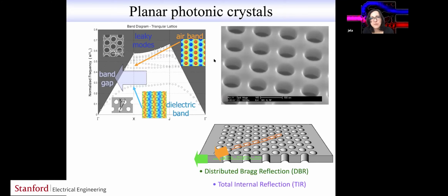So when you plot this band diagram for the structure, on the horizontal axis, you will have the in-plane K vector, right? You just plot the K vector in the plane where you have epsilon periodic. So for us, that would be this XY plane or KX-KY plane. And these are different points, which we will calculate in a moment. And on the vertical axis, you have some frequency or normalized frequency. And we'll see that this solid line here is actually a light line. It's the same thing as the light line omega equal to C times K that we plotted for the omnidirectional reflector, but we'll see why it looks a little bit strange here.